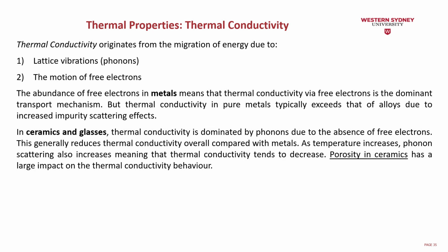In ceramics and glasses, the thermal conductivity is dominated by the phonons due to the absence of the free electrons. This is generally going to reduce the thermal conductivity overall compared with the metals. As the temperature increases, the phonon scattering also increases, meaning that the thermal conductivity tends to decrease. The porosity in the ceramic has a large impact on the thermal conductivity behavior.